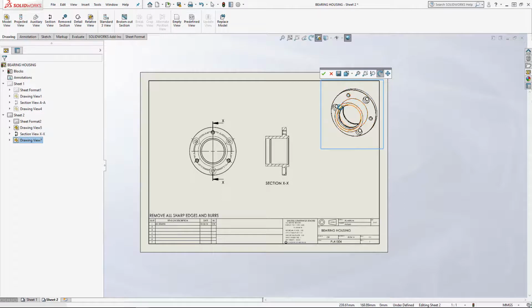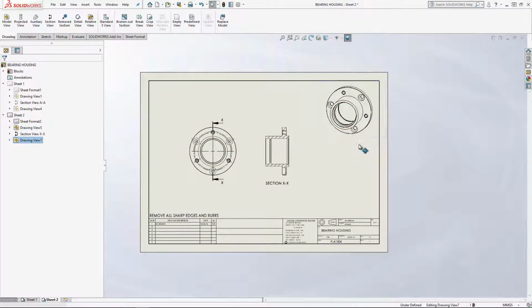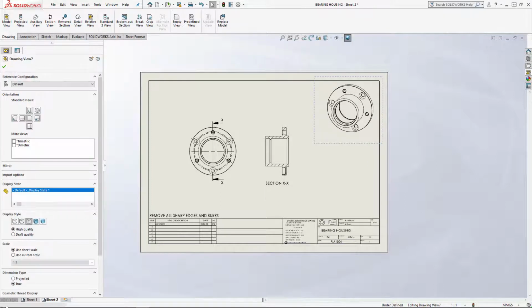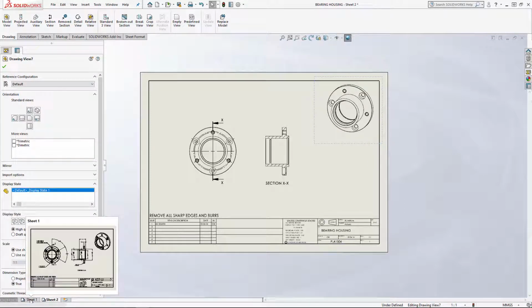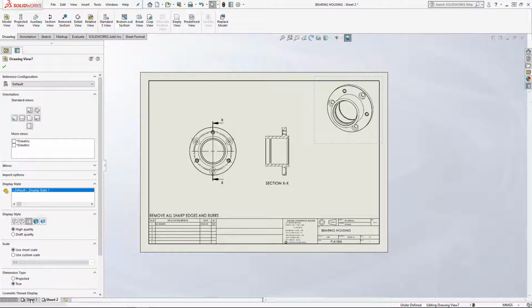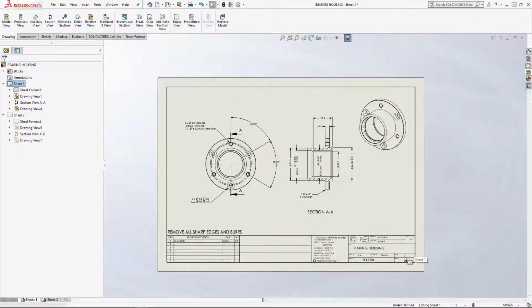The general rule of thumb there is you want to show as many of the features of the part as you can and give a sense of, for want of a better word, 3D-ness of the part that you don't get in these 2D views. You have to sort of use your imagination with these. So yeah, that'll do for our purposes there. I'm thinking maybe the sheet scale is slightly different on the first sheet. Oh no, it's the same. I thought that these views looked slightly bigger.